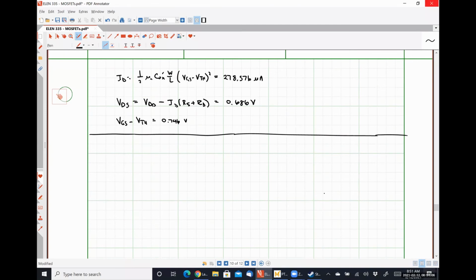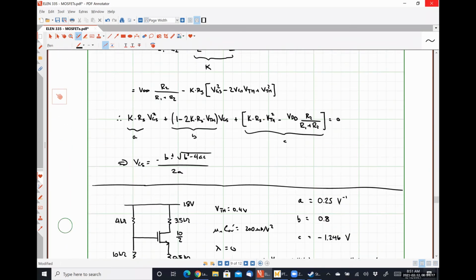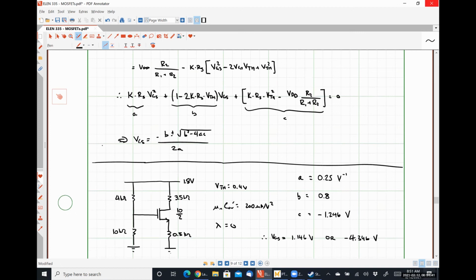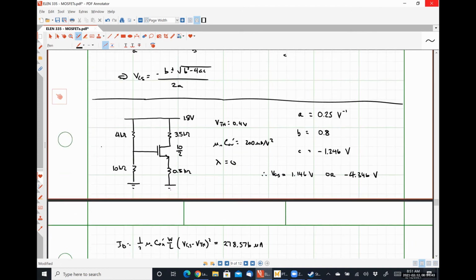All right, so in the triode region, let's start with what we have here, okay? Everything that we have done really is okay, except we're using the wrong equation for the current. Yes? All this works for the PMOS as well. Yep, everything, just change the subscripts and use VTHP, and everything that we're doing works.